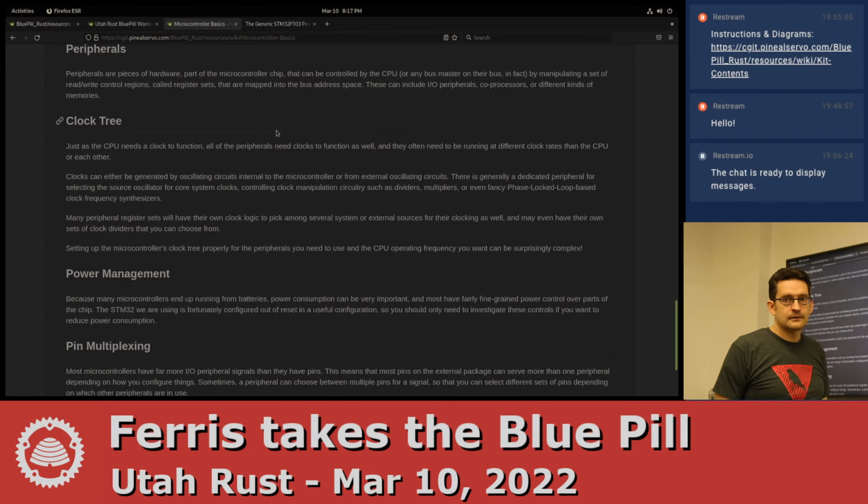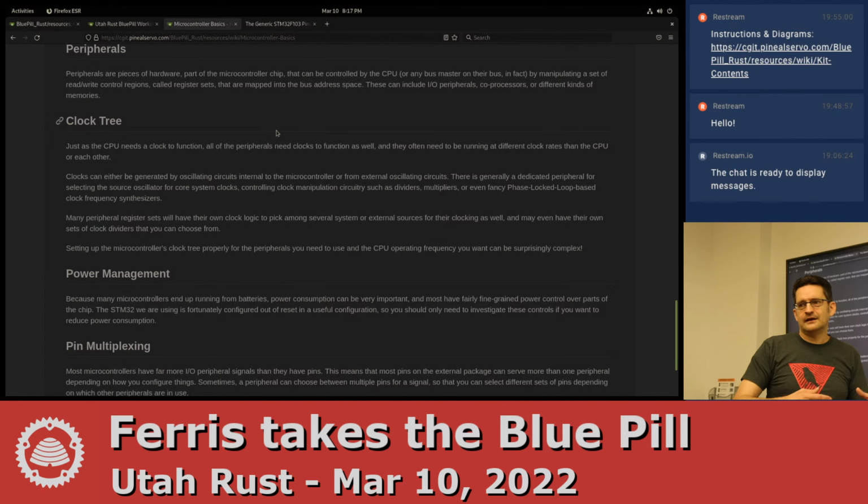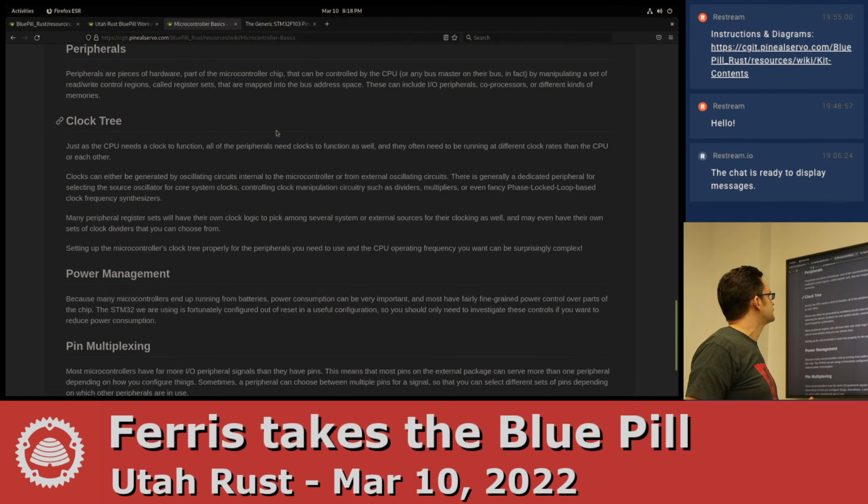There will be a whole complicated API that we'll introduce later about how to write to those safely and get the correct values written in. Because control registers tend to be broken into fields, you've got a 32-bit value you're going to write, and some bits of it mean one thing and some bits mean another. In the world of C programming, this meant that you had to use bit masks and shifting and all sorts of things to build up one of these register values. But we've got handy tools in Rust to make that much easier and less error prone.